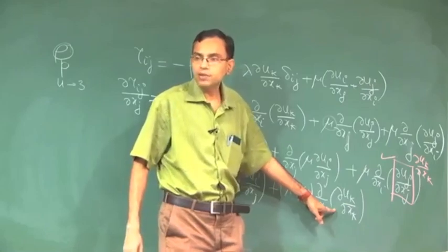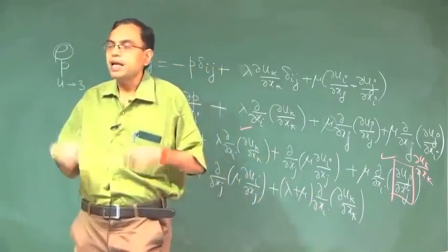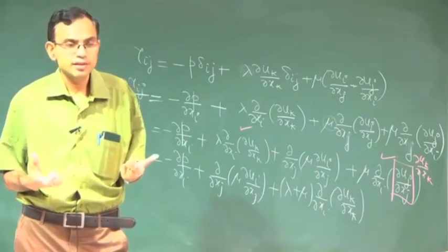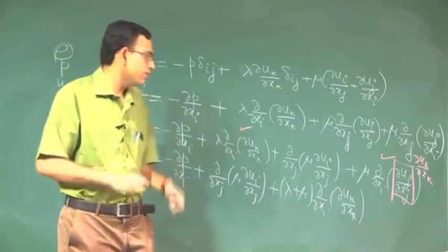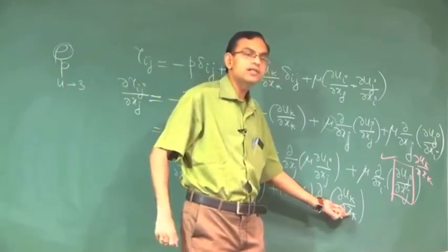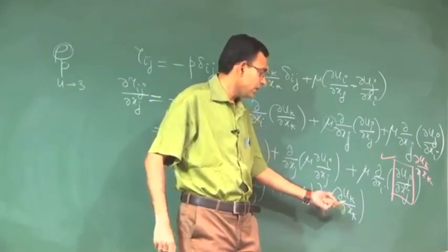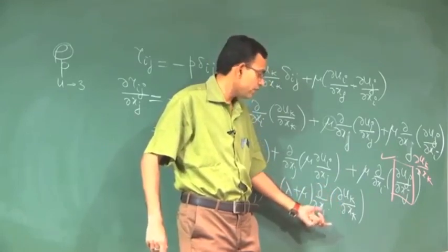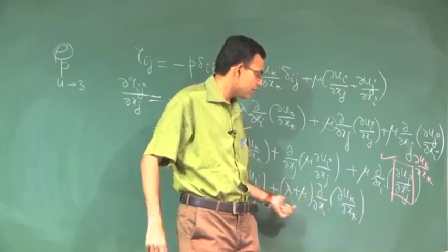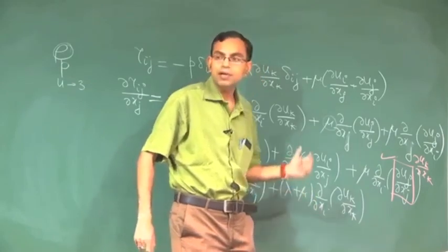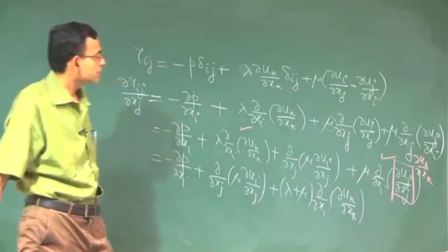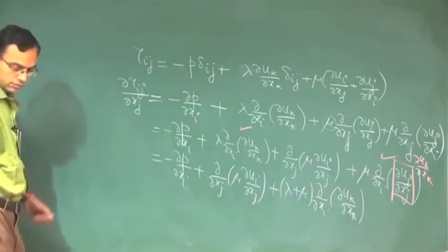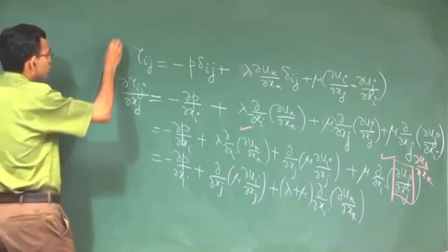For incompressible flow this term does not matter. So, for incompressible flow the parameter lambda is irrelevant, it is not at all important what it is, but for compressible flow this term is not 0 and therefore there is a chance that it has a spatial derivative, and therefore one needs to recognize the relationship between lambda and mu. So, to do that